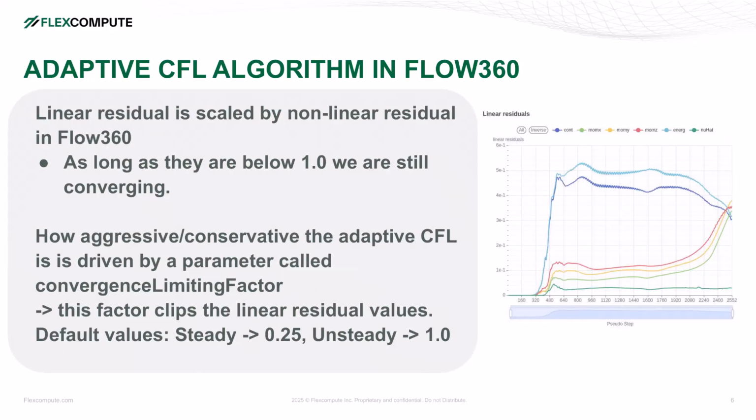By default, the convergence limiting factor is set to a conservative value. This was chosen so that a wide variety of cases converge without requiring the user to tune settings. With the addition of the smart CFL cut logic, the default is likely more conservative than necessary for many production cases. In practice, for typical steady simulations, you can often increase this value moderately to speed up convergence, as long as you monitor residuals and solution behavior.